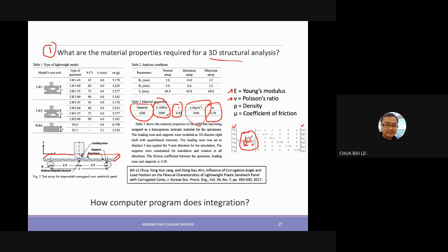So how do you obtain all these Young modulus and Poisson ratios? Again, we assume the material is homogeneous or perfect. No notch, no defect. So we may take the Young modulus from the appendix of your material design textbook for the particular material. That is where it comes into play, to estimate. Remember, whatever you learn, finite element is to estimate, or to approximate what would happen.